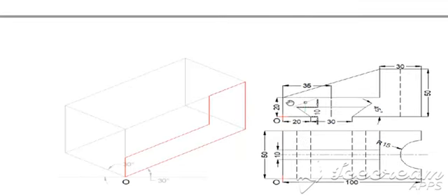Here we can simplify this problem. Instead of taking this slot and this rib, consider this as simply an L. This L, we can see in the top view again is extruded widthwise. So first draw that L by using these distances. So length is 100 mm, height is given as 50 mm, then again top of the L is 30 mm. On this side the height is 20 mm, here you can see that 20 mm.